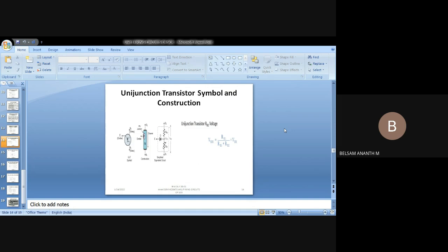And the next one is the unijunction transistor concept. You all know about UJT, the unijunction transistor; we already discussed it. You have two bases and one emitter. And please remember, in order to get the voltage divider value, for example, when I have two resistances connected in series and I want to find out my voltage, the resistance connected across the voltage source, that value, is divided by the combination of the resistances.